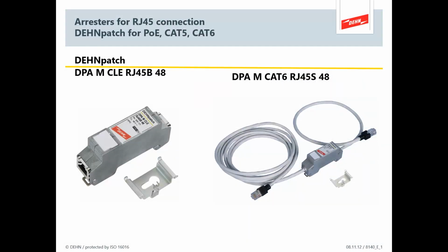In addition, we also protect Ethernet lines. So you can either have an RJ45 connection in and out, and the earthing arrangement is via the metal chassis to the DIN rail. And in another case, we have an SPD which has already got cables pre-made. So you just have short connections within, say, a 19-inch rack arrangement in your hub.